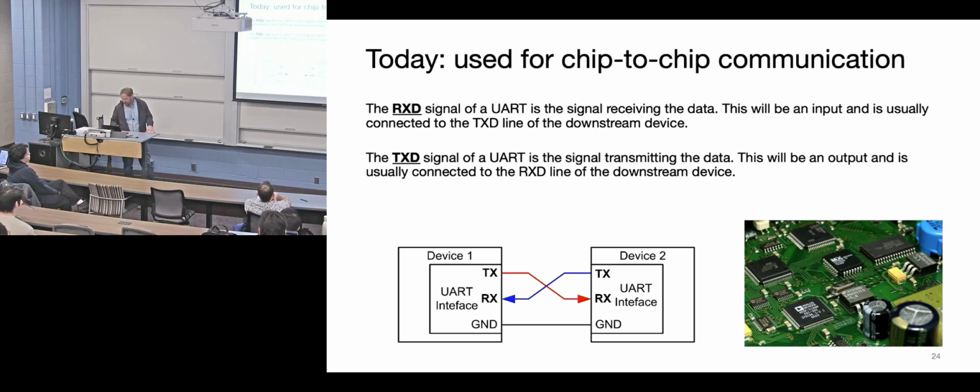What's the build here? This is predicated on being a relatively old communication modality. This is the way computers were networked in the late 70s, early 70s. And we always have to remember there's ground. On your projects, remember you have to connect ground between devices. Every year we seem to see a case where somebody's trying to do serial communication and they forgot to add ground. So it's not just 2 wires, it's that plus ground.